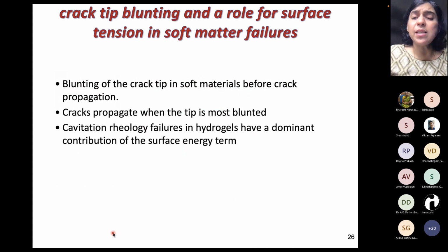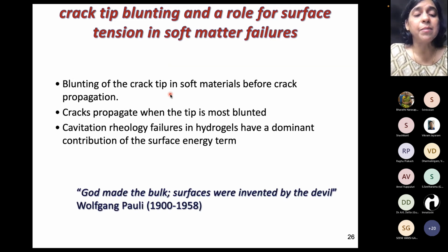So these are some of the novel features that we have found: the blunting of the crack tip seems to be a very nice feature in soft materials, and the cracks propagate when the tip is at its most blunt. And cavitation rheology has this dominant contribution of the surface energy term.